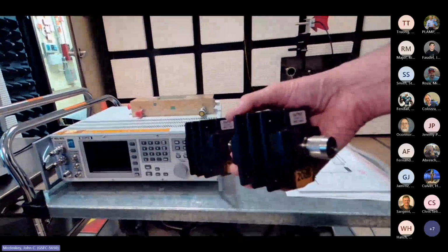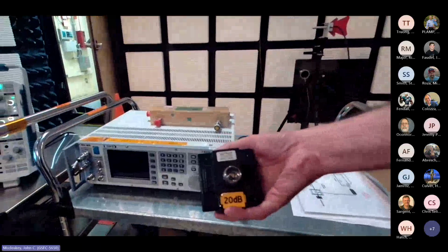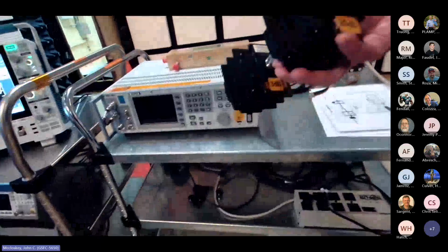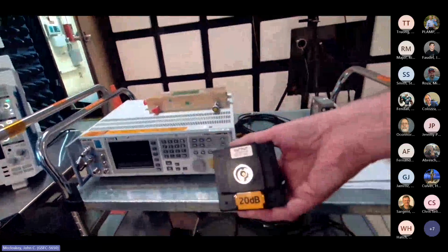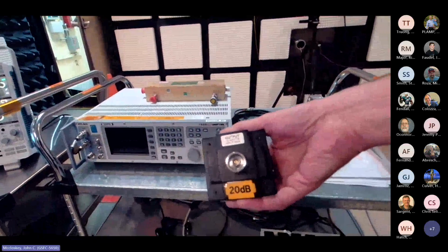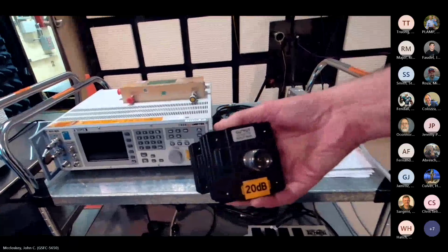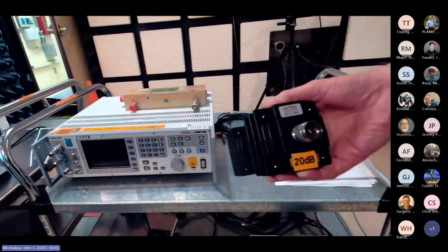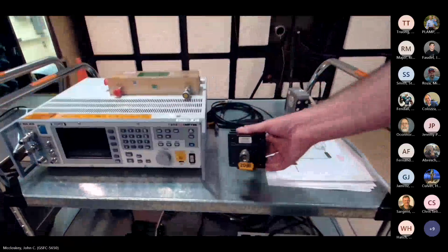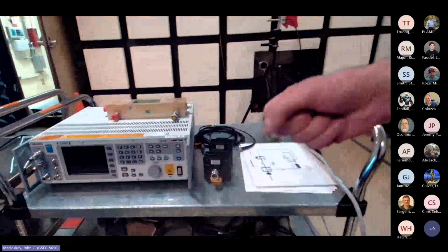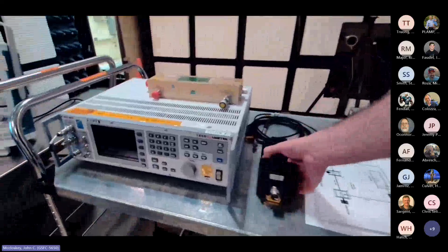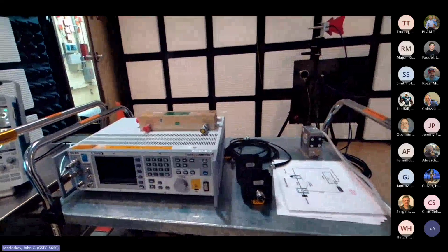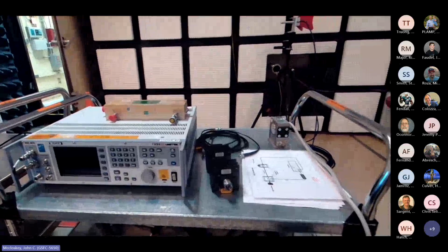So this first attenuator is 20 dB. That's pretty big lettering. I think you should be able to read that. The second one's 3 dB. So a total of 23 dB. That's a factor of 200 in power. Okay, so that's knocking the available power down by a factor of 200. So for a 500 watt amplifier, that's hardware limiting you to about 2.5 watts that you can inject. That's a much safer level and more reasonable for most of what we do.